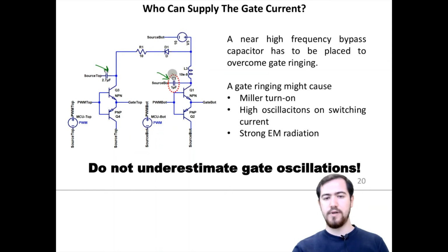So in general, we use a ceramic capacitor for this type of usage, and it gets charged through this voltage source in a small amount of time, with a small amount of current. However, it supplies the immediate current requirements to the MOSFET to activate its gate.